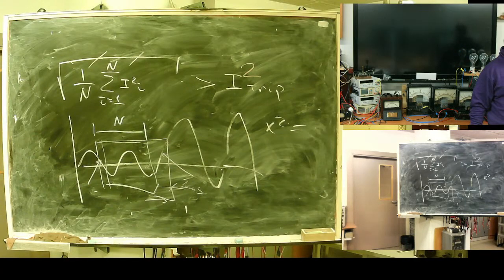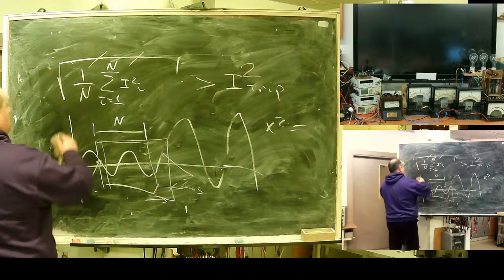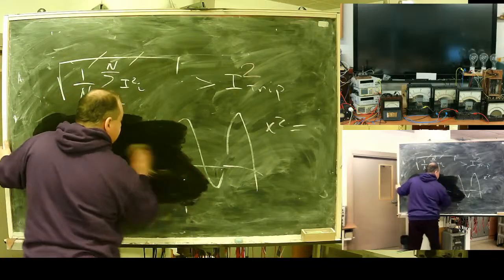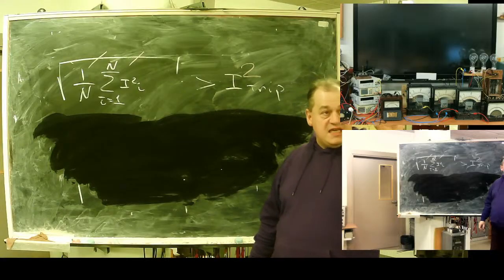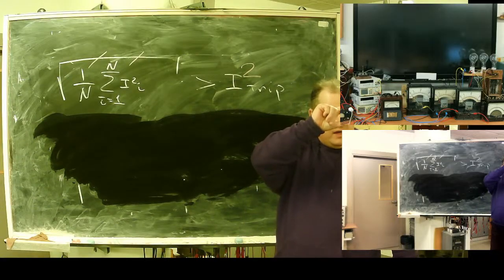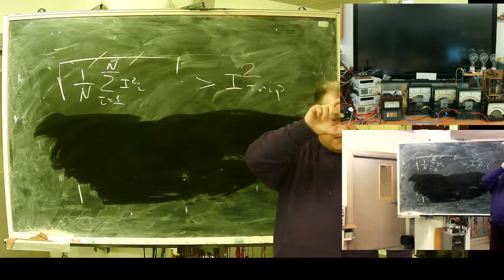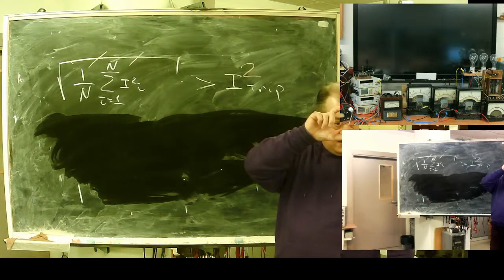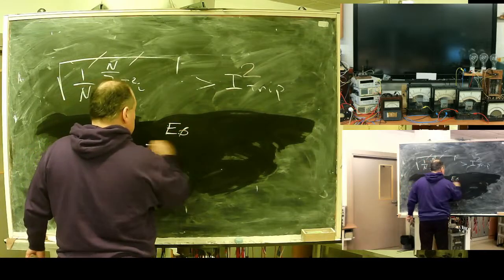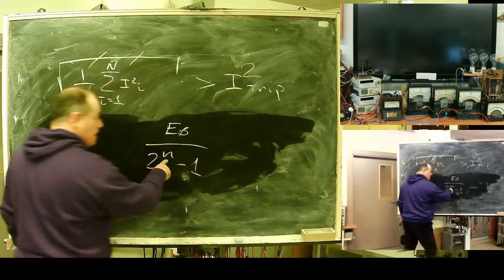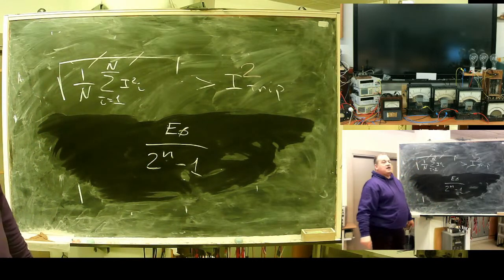Hysteresis. Remember this word? Hysteresis. In reality, I will have some kind of jitter. Also, remember what ADC gives me? ADC produces steps. The values in the vertical, in magnitudes, are discrete. They come with steps, A0 divided by 2 to the n, where n is the number of bits in the ADC. That's one moment.